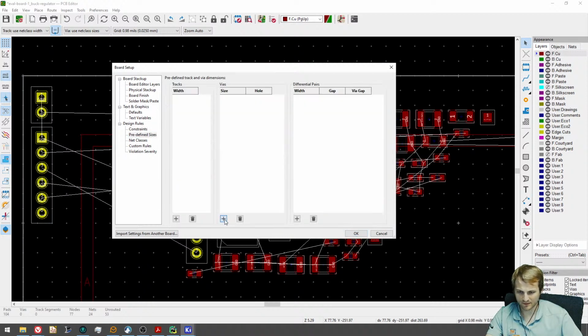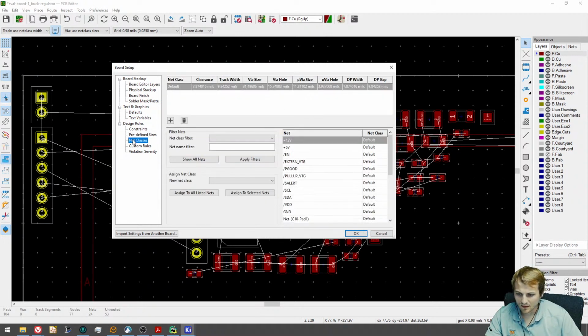And then for vias, my standard via will be 25 mil hole with, let's start with 30 mil hole and then I don't know, we can try 50 here and see how that is, because they typically will upcharge you if it's 25 mil hole, but we can see. And then here, clearance 6, 6. Via will do the same thing. So 25 and 50.